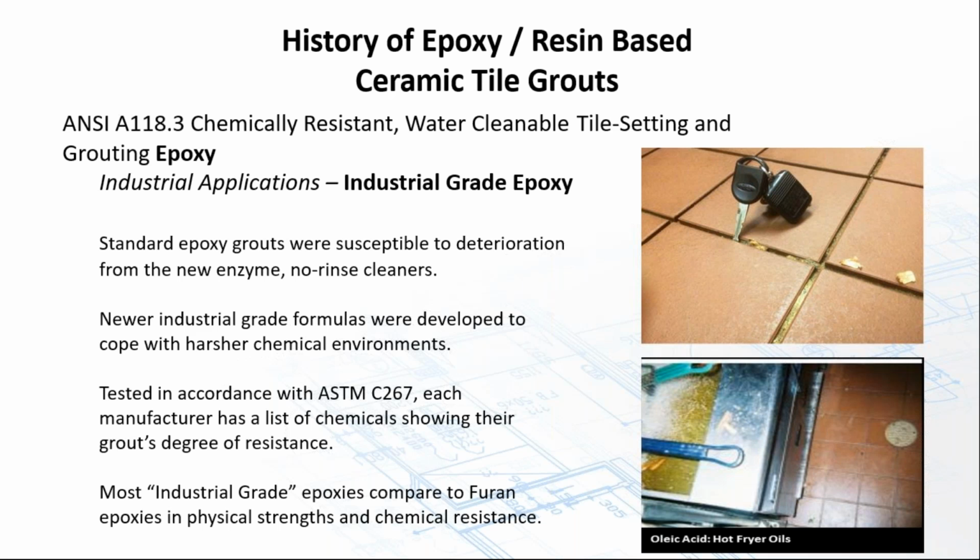All well and good. What ended up happening is that in the testing of these cleaners, we didn't recognize, or the industry didn't recognize, what would happen when they were mixed in with certain food products, and how that would attack the grout. What we found out is that these cleaners mixed with certain food products, especially olive oils and chicken fat, form what's called an oleic acid. This oleic acid is very caustic and will eat up a traditional epoxy grout.